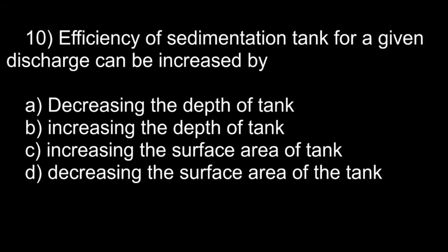10th question. Efficiency of sedimentation tank for a given discharge can be increased by option A, decreasing the depth of tank, option B, increasing the depth of tank, option C, increasing the surface area of tank, and option D, decreasing the surface area of tank. Efficiency of sedimentation tank can be increased by increasing the surface area of the tank. If the surface area is more, the sedimentation efficiency will also be more. So option C is the answer. Option C is the answer.